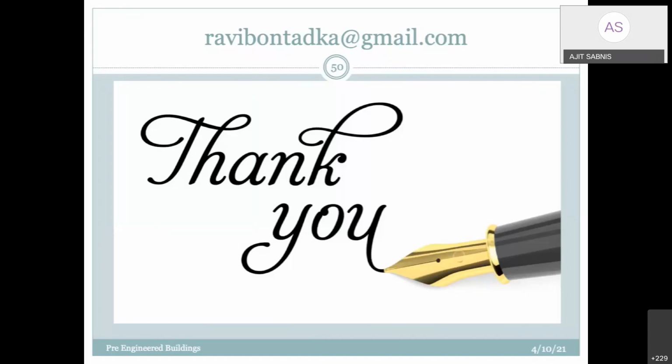Please go ahead. See, basically a steel structure with all its convenience and flexibility is only as strong as its weakest link. So that's why connections are more important. If a connection is weak, there is no point in the members or the whole framework being as strong and designed properly. Finally, it fails in the connections. So we should be very careful about the connections and detailing.